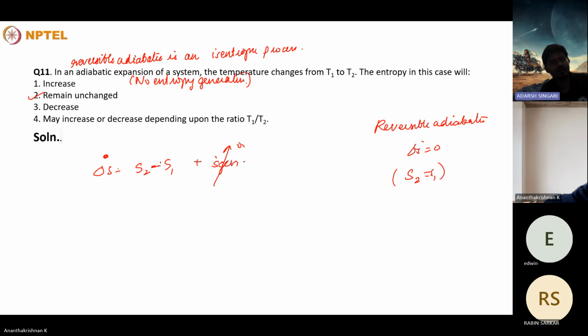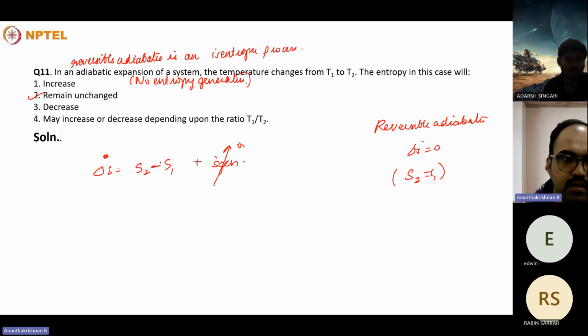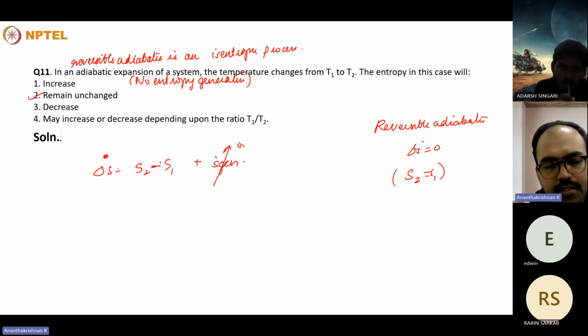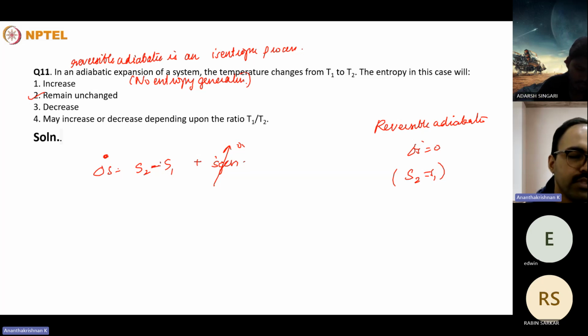For insulating and adiabatic, both the cases, for liquid and gas. Insulating means it will be adiabatic only. There will not be heat transfer. Adiabatic also means Q equal to 0 for both liquid and gas. It has got nothing to do with whether it's a liquid or gas, right? Adiabatic is a boundary condition, so there will not be heat transfer between the outside surroundings and the inside zone through the boundary.